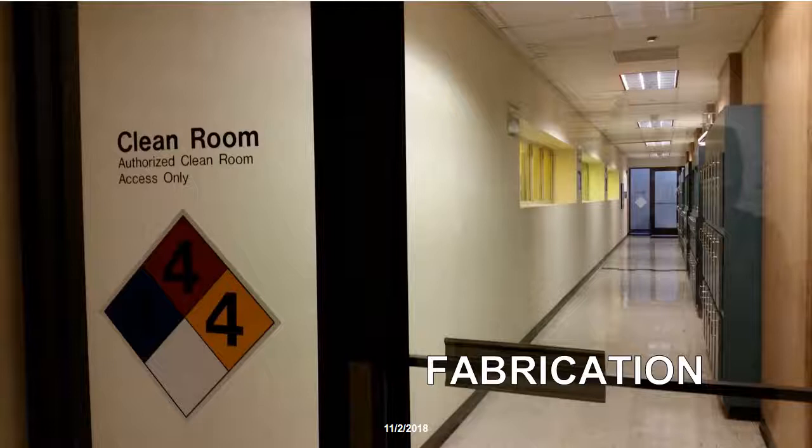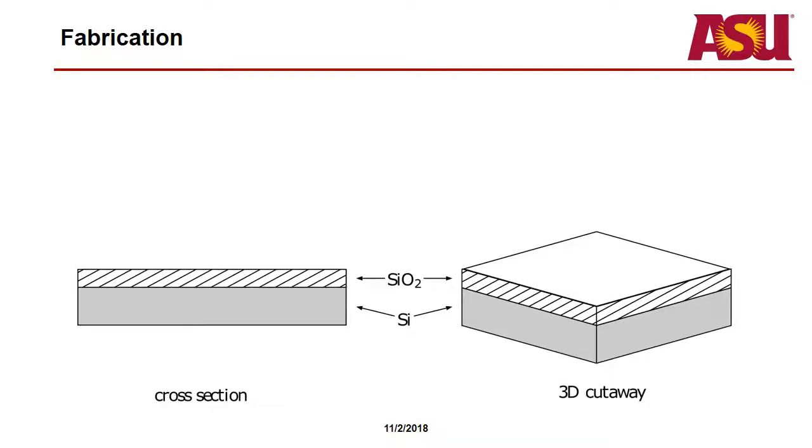Okay, so next I'm going to get into the fabrication of the CB-RAM devices. First we start with a silicon wafer, and we deposit about 100 nanometers of SiO2 on top just to isolate the silicon from the rest of the devices.